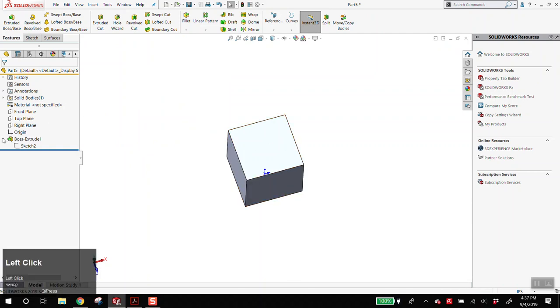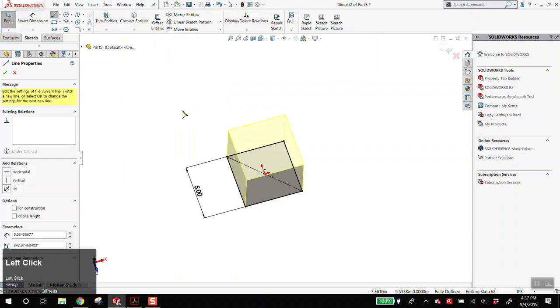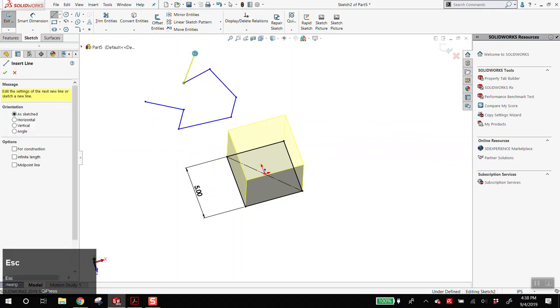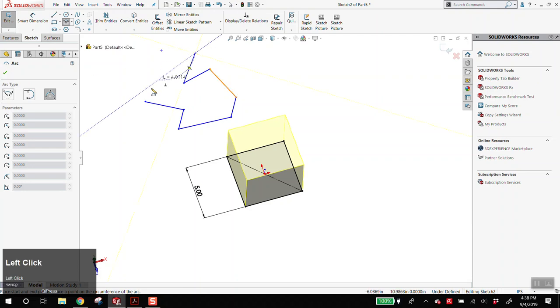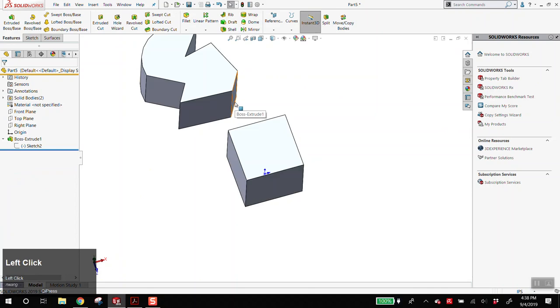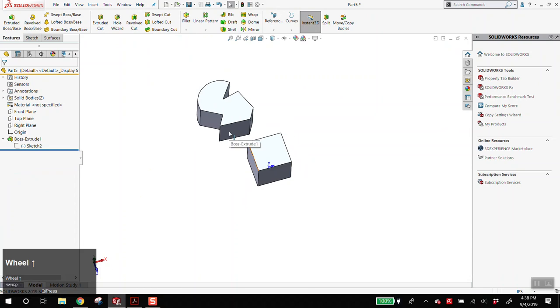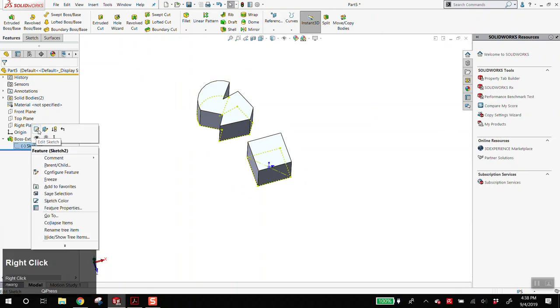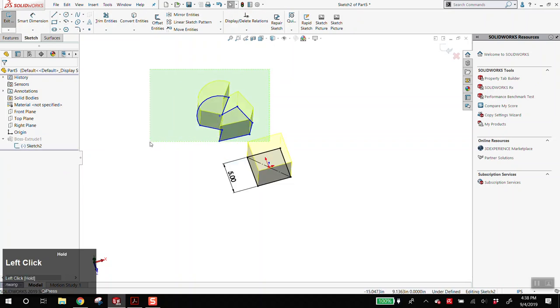All right. So again, extrude, essentially whatever shape you draw. You know, if I draw something silly here like this. Oh, no worries. And if I add some curvature to it, whatever shape you draw, it just takes that and makes it longer to whatever length you tell it to be. Again, think of it like pushing toothpaste out of a toothpaste tube, or a cylinder, or Play-Doh. That's an extrude. Again, probably the most basic command in SolidWorks. We started with revolves because we're working on bottles.